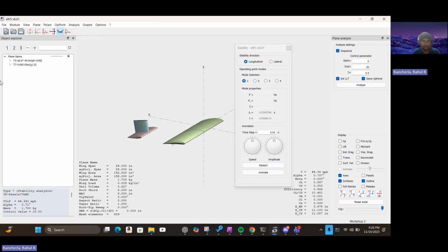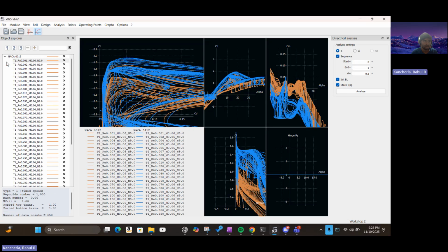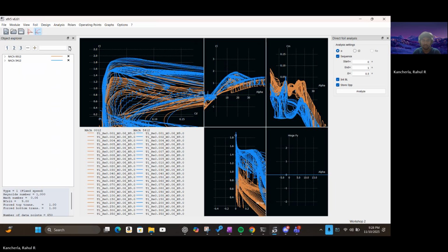So before you do any stability analysis, or any analysis in general, first you need to go back to your XFoil direct analysis, right? And I covered all of this in the first video. So if you're confused or have any doubts, you can go back to that one. Before you do any advanced analyses, I guess you could call them, you need to do batch analyses on particular airfoils, whatever airfoils you choose.